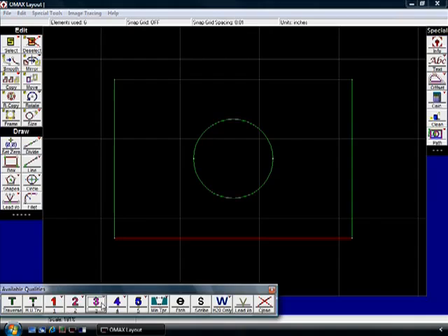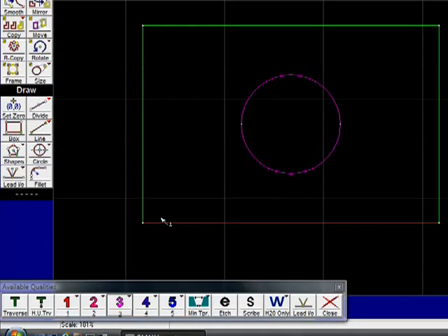And then maybe the center hole here, we want it to be a higher tolerance because we want to fit a bolt through it. So this will cause it to cut a little bit slower in this area, but the end result will be a smoother, higher tolerance surface finish. Then on the remaining pieces, I might make them quality of 2 because they just need to be cosmetically nice looking, don't have to be high tolerance, but we don't want to waste a lot of time on those. So you can optimize your tool path by choosing which areas for the machine to spend a lot of time on.